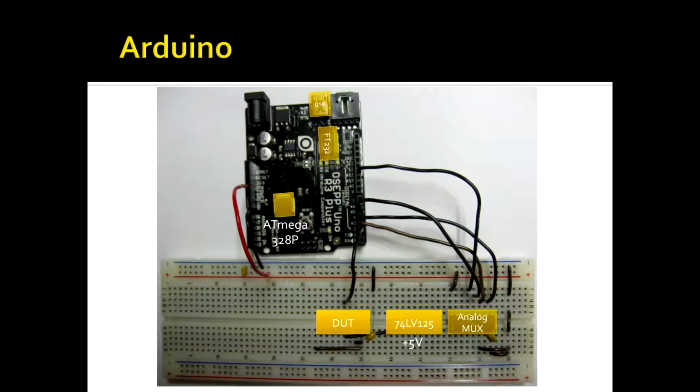So for a while, I seriously considered Arduino for about 7 minutes, because why not? And the problem with Arduino is the crystal is fixed on board. I think it's 16 megahertz. As soon as you use any of the timer or output compare registers to divide that clock down, you can't take the 16 megahertz and provide it directly as 16 megahertz on an output pin.